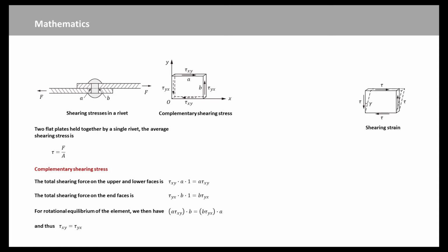We see that whenever there is a shear stress over a plane passing through a given line, there must be an equal complementary shear stress on a plane perpendicular to the given plane and passing through the given line. The directions of the two shear stresses must be either both towards or both away from the line of intersection of the two planes in which they act.